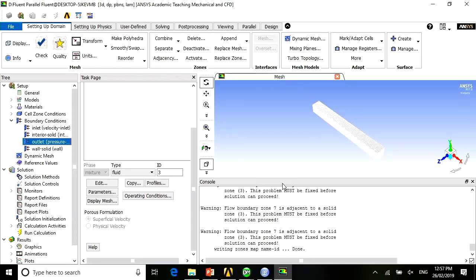Okay? Fluent, which was developed much earlier than CFX itself, solves the problem sequentially, segregated. So that means that they solve the U velocity first, solve the V, solve the W. This information of velocity goes to the pressure correction, okay, and then it goes back. So basically, this is called the segregated approach. Because you have the segregated approach, you need to make sure that the solution is well behaved by introducing under relaxation factors. Now I'm confusing you.